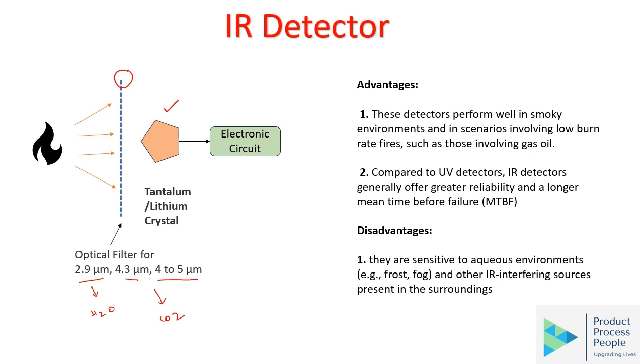So an IR detector captures the random flickering of flames in the infrared band, generating a signal that is processed by a low frequency bandpass filter before being interpreted by the microprocessor. Modern IR detectors have a high signal to noise ratio, enabling significant amplification and excellent sensitivity to the flame radiation.